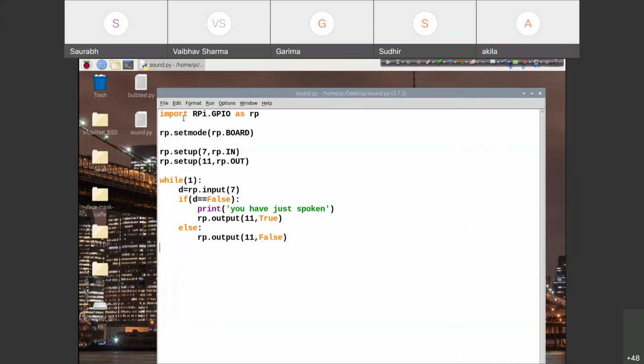Yeah, so there's a problem because this bulb will not be that fast to turn on and off in the entire operation. So let's take a little bit of time as t, and let me give a delay. However, this delay can ruin the entire operation, because a delay is going to take a huge amount of time and make this operation bad. So t dot sleep for 2 seconds, maybe 1 second for a moment. Save. I'm not giving delay to off, otherwise every time it will be in the second case.